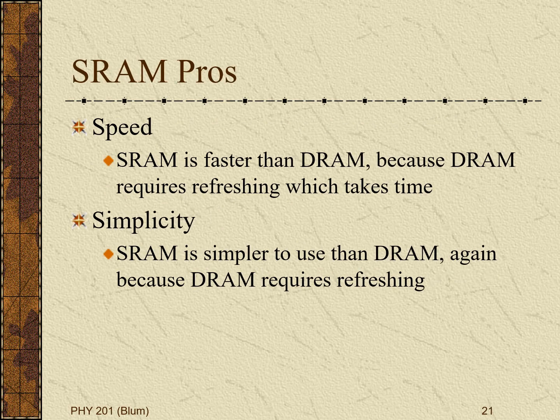So some people will ask, if you have SRAM and DRAM, if you have this faster memory and this slower memory, why don't you just use the faster memory for everything? So let's talk about the pros and cons of SRAM and DRAM. So the pros of SRAM is that it is faster and it's simpler. It doesn't require the refreshing, so you're not slowed down by the process of refreshing, and it's simpler. You just simply don't have the process of the refreshing.